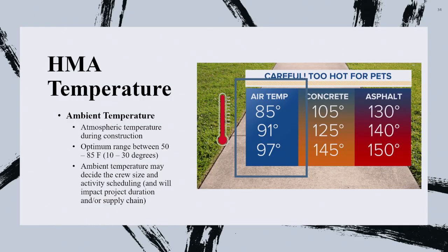Now, this one, even if it drops 10 or even more than 10, it still is not going to give you the same hard time, or the pie crust thing, as the hot mix asphalt. Even in JFK, John Kennedy, in O'Hare, Chicago, the most important airports in the US, if they want to fix the runways, they want it fast, in the middle of the night, in the middle of the winter, and Chicago could be 20 below zero. Warm mix asphalt is being used because of its ability to achieve good compaction even if it cools during transportation.